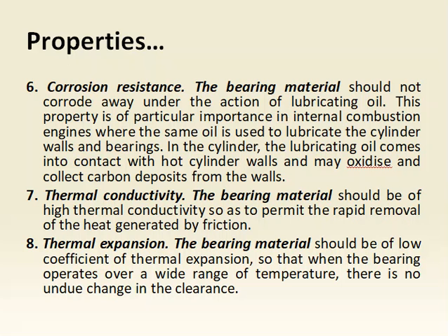That causes metal to metal contact, which creates a lot of dust, sound and noise, as well as wear and tear. That is not acceptable for any bearing material. So thermal expansion should be very low, therefore no change in clearance happens. Okay, so those are the important properties of the materials for any bearing surfaces.